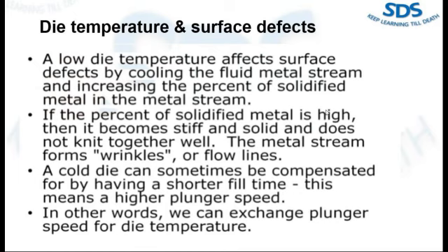What we are doing at that time is compensating for our ineffectiveness in maintaining the standard cycle time, or you can say we are not able to maintain all our parameters like die temperature, metal temperature, high speed. And the most common parameter which we are not able to maintain is the metal temperature.